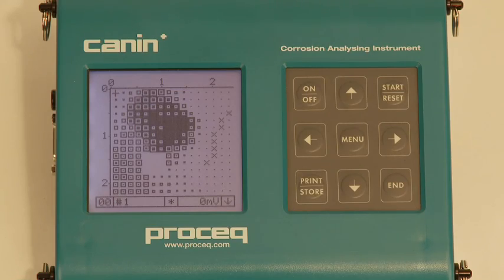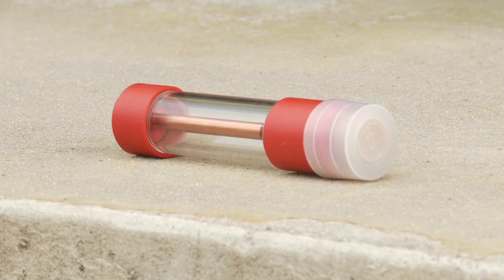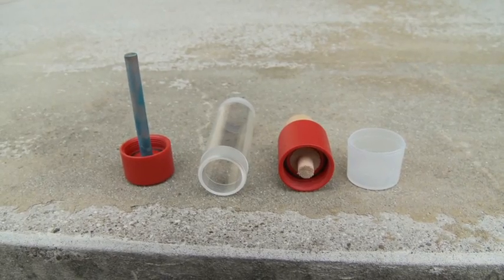Existing readings can be overwritten by moving the cursor to the appropriate point in the display and making a new reading with the electrode. Once the reading has registered, the cursor will move to the next measuring point along the axis indicated by the direction arrow. To delete an existing reading, move the cursor to the point you wish to delete and press Print for 2 seconds.